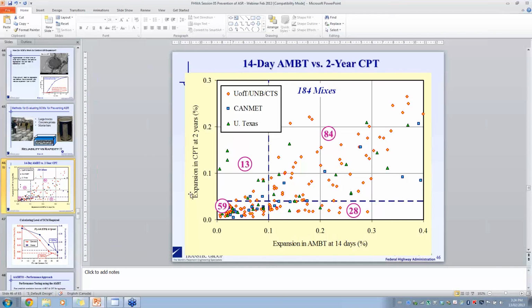Okay, the next question is, how can you test a bagged cement concrete product for ASR when the product is already blended sand and cement? Yeah. Good luck with that one. You certainly couldn't really do it by the concrete prism test. This is something that Kevin spoke to last week with the test methods. Essentially what you would want to do with a bag mix is you're basically testing a job mixture. And we don't really have a test method for doing that.